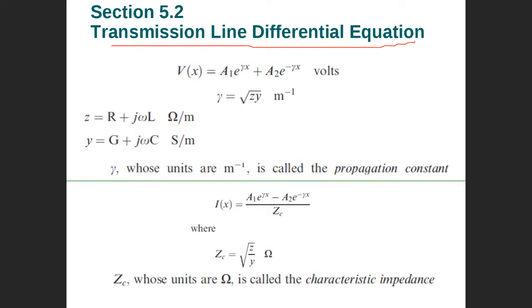But is it worth it sometimes if the line is short? Short means maybe 25 or 30 kilometers or 20 kilometers, for example. It isn't worth it to model it as a long transmission line. So it will be perfect to model it as a medium or short transmission line. The short transmission line will also give us a rough estimate.